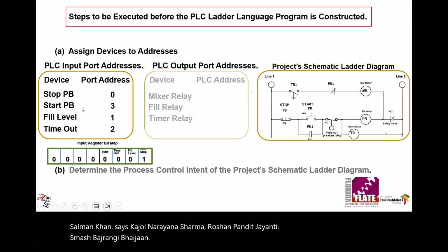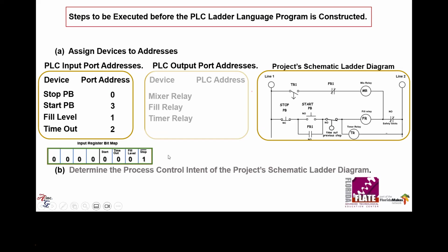Notice there's something else going on here. I did it this way so you could see the labeling of stop and start. They're at extremes. One's at the right-hand side, and the other's on the left. That's a very common practice done to cut down the possibility of the technician who has to do something with the wire associated with the stop not accidentally doing it with the start. It could still happen, but at least it's not right next to it.